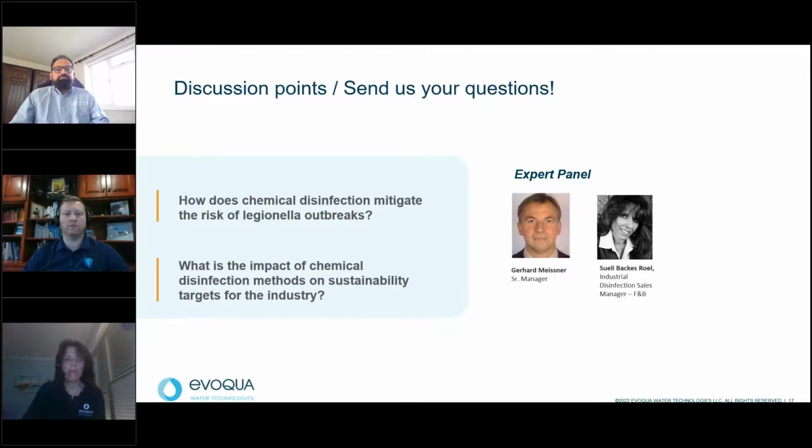Any disinfection will be more efficient if you add filtration to remove these particulates, which can first be aging in the pipeline, second act as nutrition for eventually surviving microorganisms, and last, also to remove the particles from the circuit. That's the only thing I have to add.